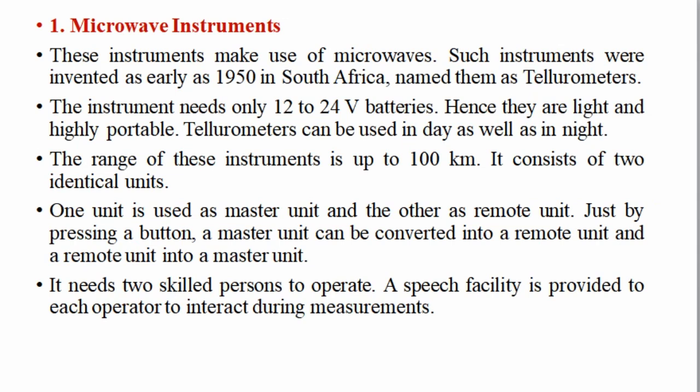The instrument needs only 12 to 24 volt batteries. Hence, they are light and highly portable. Tellurimeter can be used in the day as well as at night. The range of this instrument is up to 100 km.